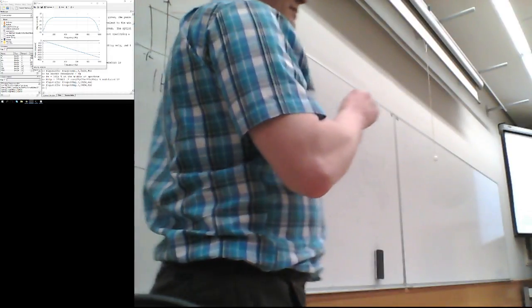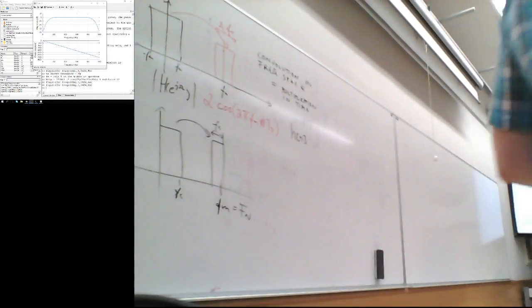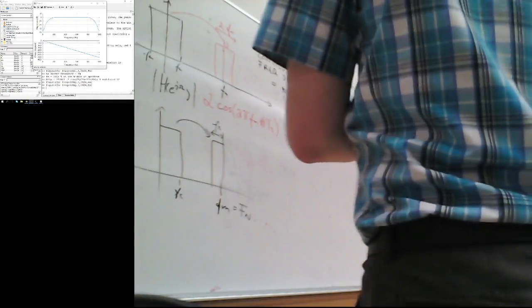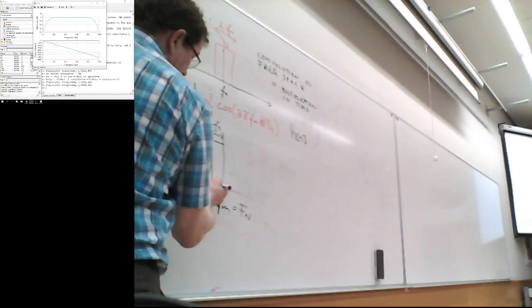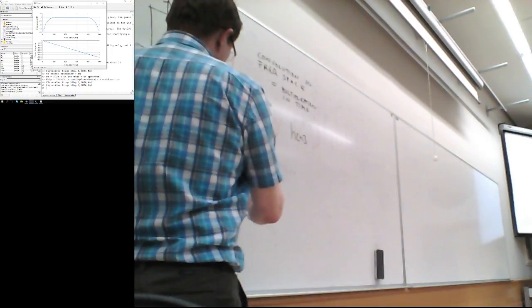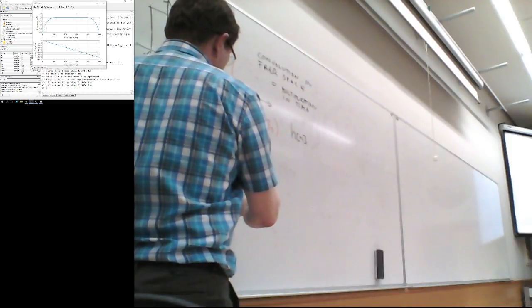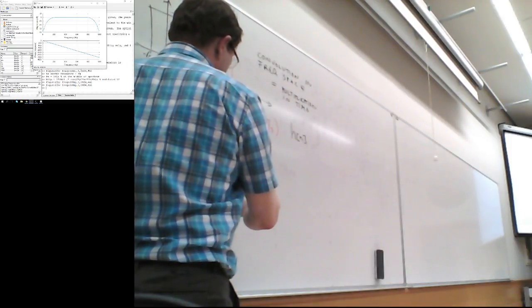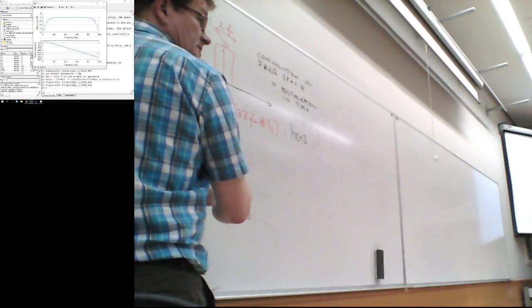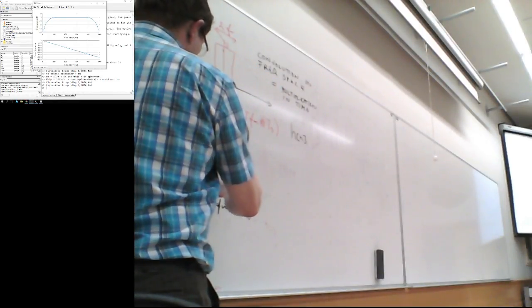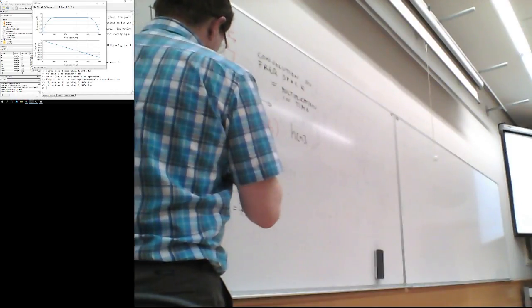Okay, there is a trick in the exercise. When you're doing the exercise, I'm actually defining the cutoff frequency of the high pass filter somewhere here. So first you need to think of what is the bandwidth of this high pass filter, so that you will design this low pass filter correspondingly. That doesn't look the same anyways.